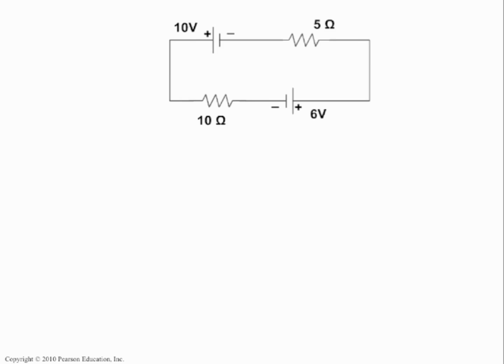So it is kind of weird for students at first when they do Kirchhoff's rules because they're not used to having to guess. But when you do circuit analysis with Kirchhoff's rules, you actually have to guess. And in fact, it's your first step. All right, we're going to guess that the current goes this way, that I goes around in this counterclockwise fashion.